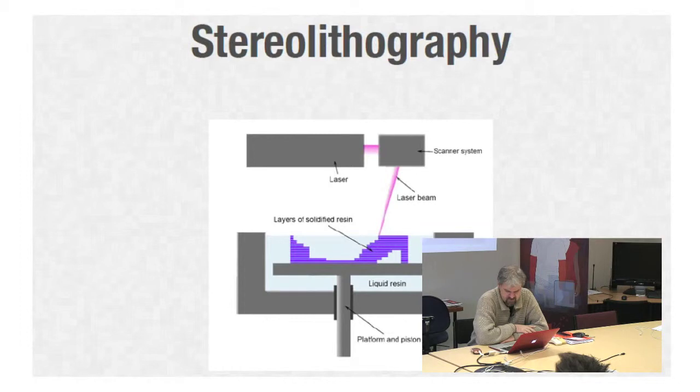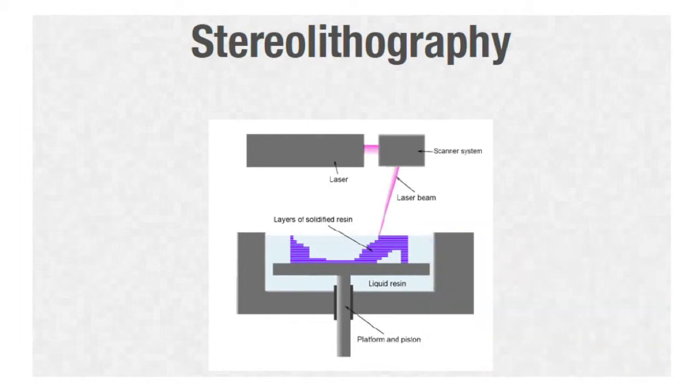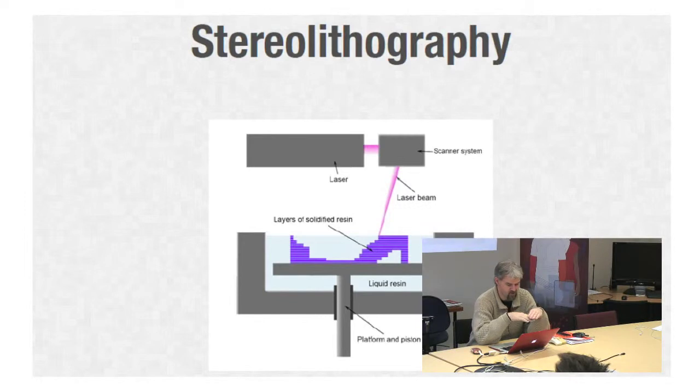So what stereolithography does is it has a liquid resin, and they use a laser to heat the resin, and when they heat it, it solidifies. Basically, over time, you'll see a 3D object starting to emerge from a bath of liquid material. Then you slowly move down this piston, and you let the laser heat the top layer, and it produces a 3D model. Because it's completely liquid, the objects can be quite complicated, and they can be hollow inside or concave and things like that.